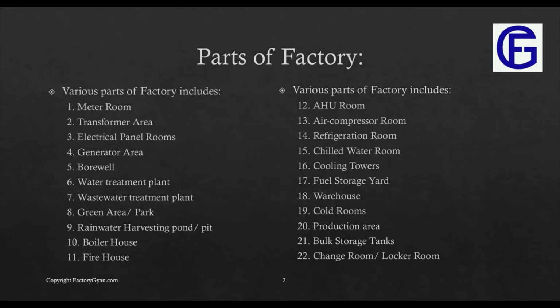Then some of the processes require chilled water, a lot of chilled water. So you can have a separate dedicated chilled water room where all the screw compressors and York compressors, etc., will be available, which will be generating the chilled water, and then you will be supplying it all across the factory. And you can have the chillers, water chillers, even near to the production plant or near to the machinery also, if the size is not that big.